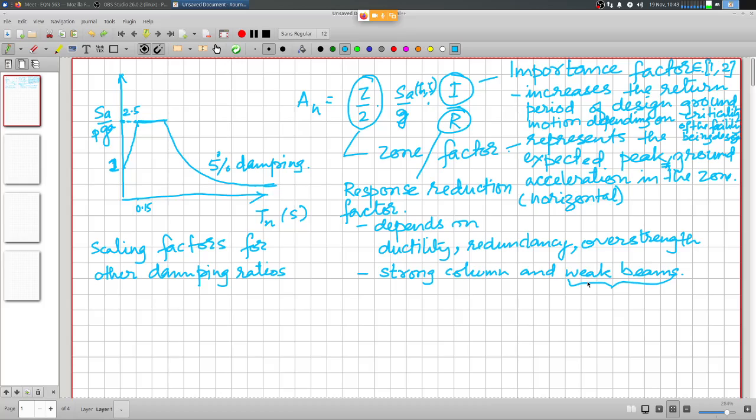that the beam capacities will always remain smaller than the column capacities, unless I know for sure that the reinforcement that I am using in the beam corresponds to the assumptions that were made during the design calculations, right? The reinforcing steel actually being used is according to the assumptions in the design.